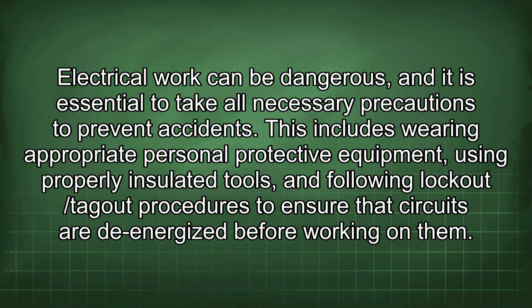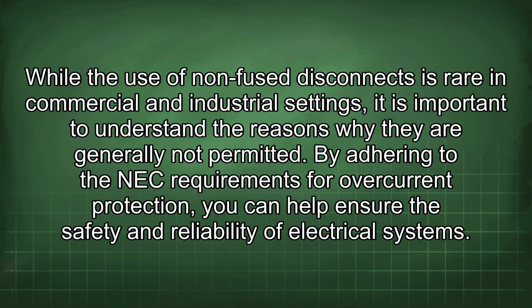Electrical work can be dangerous, and it is essential to take all necessary precautions to prevent accidents. This includes wearing appropriate personal protective equipment, using properly insulated tools, and following lockout/tagout procedures to ensure that circuits are de-energized before working on them. While the use of non-fused disconnects is rare in commercial and industrial settings, it is important to understand the reasons why they are generally not permitted. By adhering to the NEC requirements for overcurrent protection, you can help ensure the safety and reliability of electrical systems.